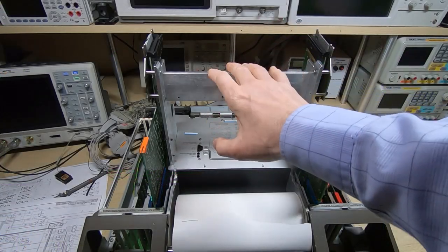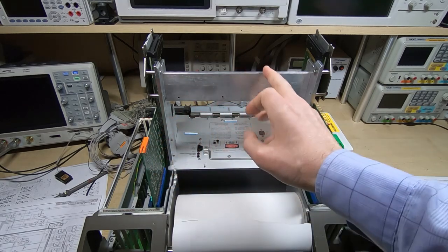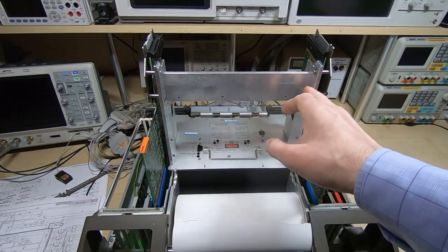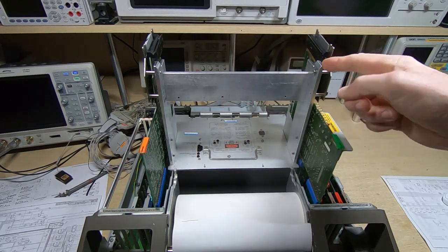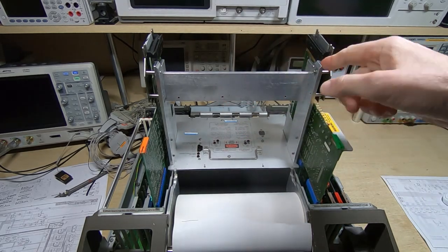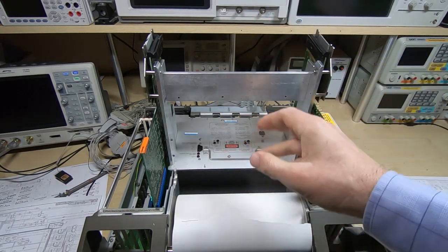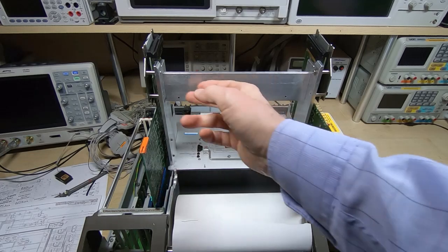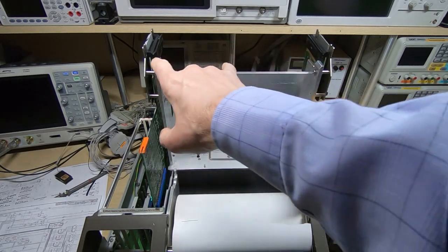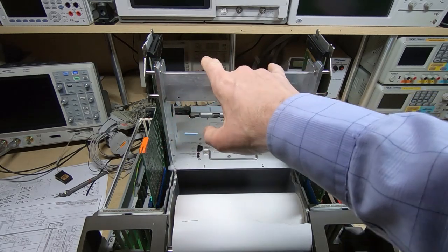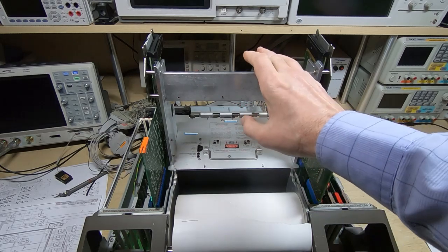Had to remove the monitor, of course, so I can get this board out to replace the faulty device. So I thought I'd just quickly show you the frame. It's fairly rigid, it doesn't move around at all, so it's not going to damage the boards or the monitor connectors, and it just makes working on this much easier. But if you're going to do this, make sure that you do something that's very rigid. It mustn't move around, and also the spacing between these is very important. If it's not correct, you'll damage the connectors on the monitor.